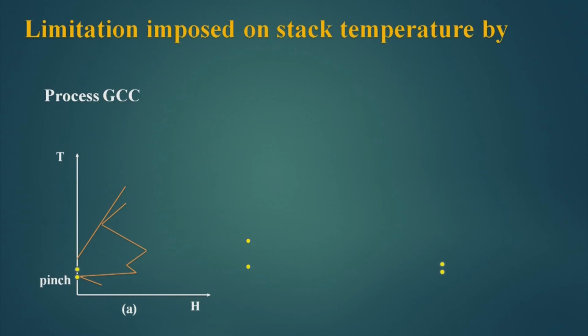And in such cases, what can we do to decrease the stack loss? We can preheat the air with the heat which is available with the hot gas, and can thus improve the efficiency of the furnace.